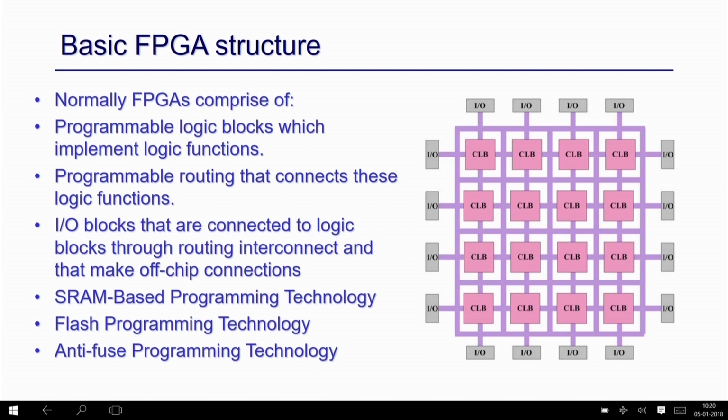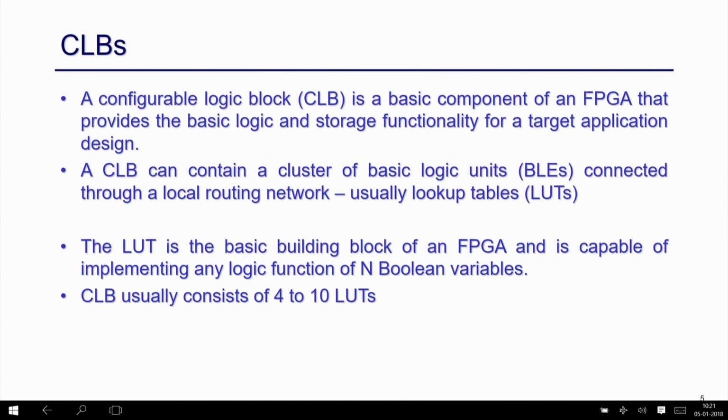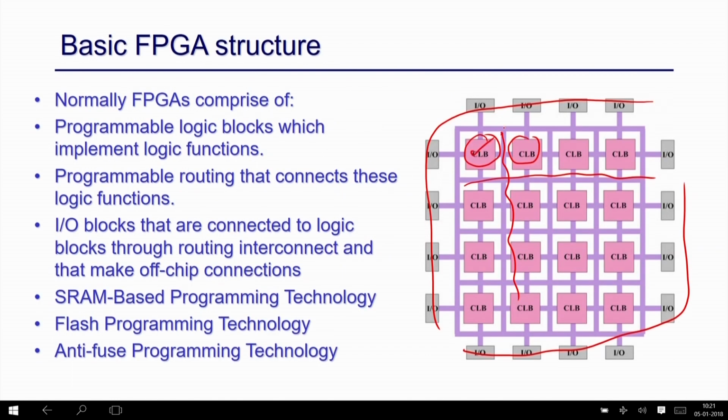Okay. So if you look into the FPGA in detail, this is the overall structure of an FPGA. It consists of sets of logic blocks, configurable logic blocks. They are laid out in arrays, and they are interconnected through these interconnection units, right? The IOs are usually placed on the outer interface. And this configurable logic block is basically configurable, so you can map your design there. It consists of both storage as well as logic units. Your design has to be mapped here, and the interconnection has to be done through this interconnection unit. All these logic blocks are programmable, and the interconnection is also programmable. So you can make a connection from anywhere to anywhere, right? Anywhere the connection can be made through these interconnections.